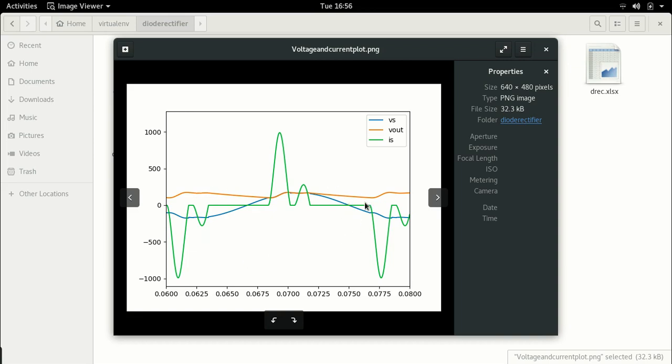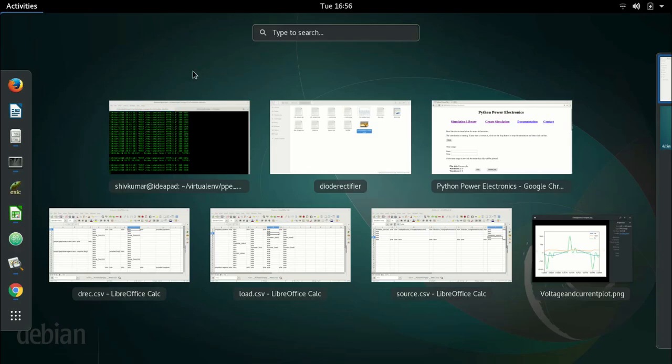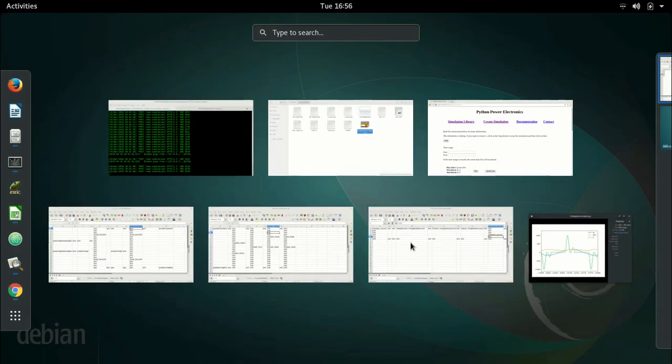When you are designing your diode rectifier, this inductor, and I'll just go back, in reality is the leakage reactance of a transformer. Nobody actually connects an inductor. Very few people actually connect a large inductor at the input of a diode rectifier. Why would you want to spend all that money there?